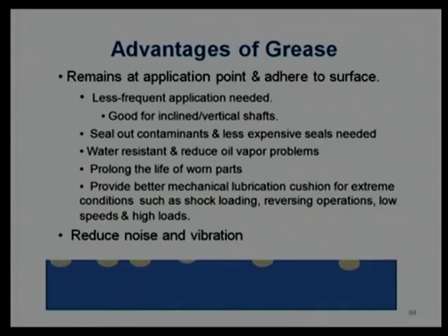And if we are using the greases, what will happen in the situation? Grease will fill these pits. When the pits are filled, then vibration level will be reduced. They will act as a damper. They will act as a noise reduction agent. They will reduce the noise overall. So, grease is effective to reduce the noise, to reduce the vibration, to reduce the impact loading on the surface. They have capabilities to absorb the energy by deflecting from the surface and regaining the shape.